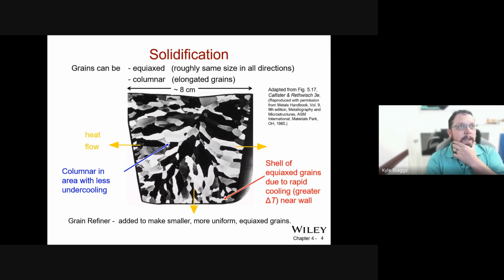So that's how we get from the molten state to this kind of crystalline arrangement. So you can see where the material usually flows in from the center. The shell has done what's called, it has equiaxed in order to have similar grains as it fills the outside. So it starts cooling immediately at the outside at a uniform rate.